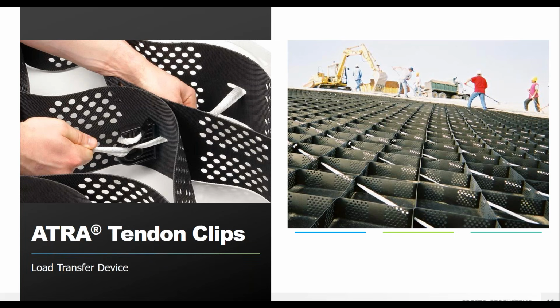So our ATRA tendon clips transfer the load from your heavy infill material to the tendons, which are those white strings that are going through the GEOWEB panels, and then up to your crest anchorage system. Crest anchorage can be something like a dead man anchor, so a buried pipe in an anchor trench.